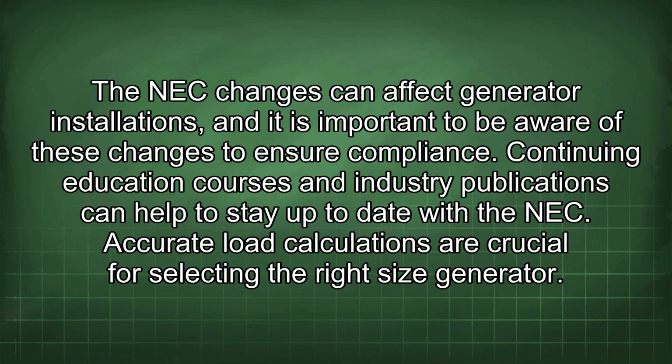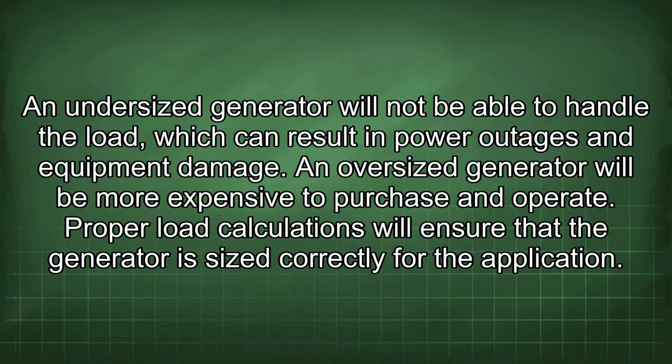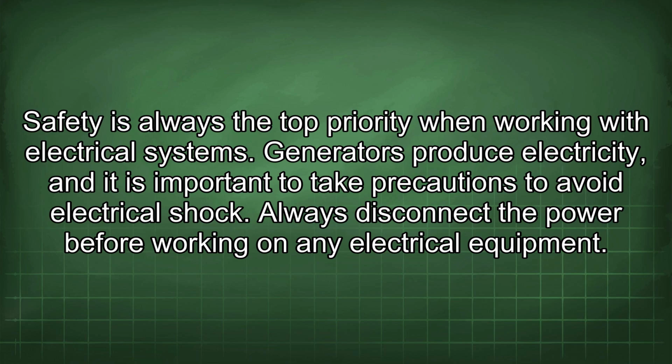Accurate load calculations are crucial for selecting the right size generator. An undersized generator will not be able to handle the load, which can result in power outages and equipment damage. An oversized generator will be more expensive to purchase and operate. Proper load calculations will ensure that the generator is sized correctly for the application. Safety is always the top priority when working with electrical systems.